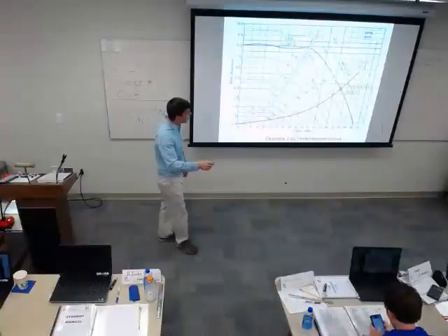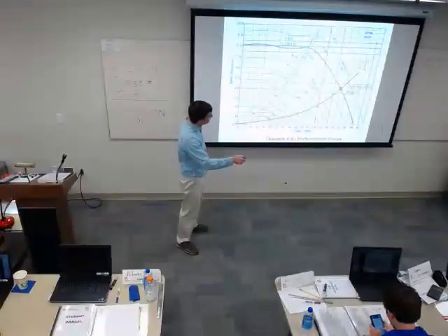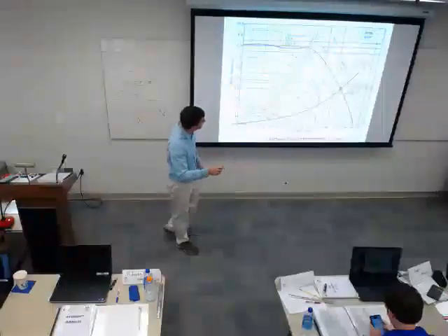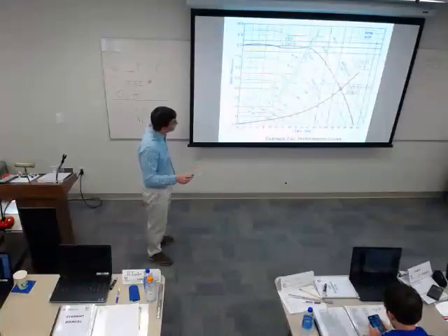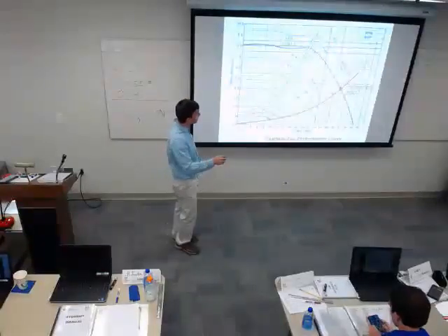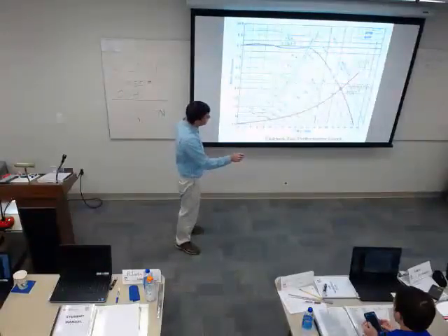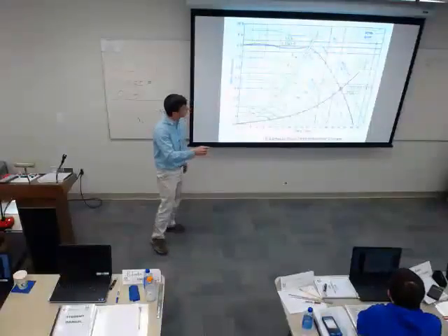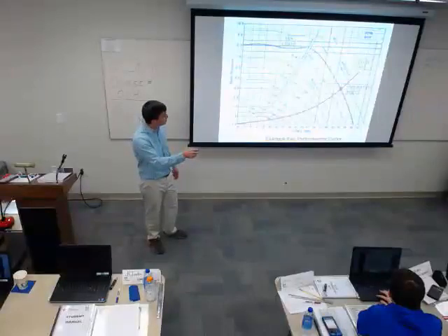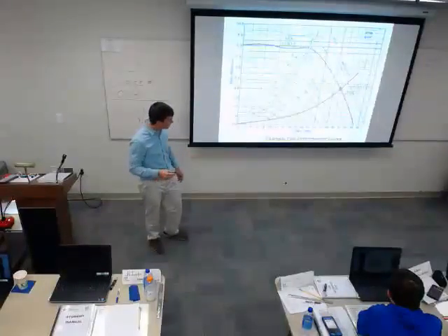Going back to one other concept here, what size fan motor would I need to accomplish this? That's not really part of this, but I want to throw that in there. My horsepower curves, these red ones: I heard 30 and 40. I would need 40. If I was operating here, I would be somewhere in between 30 and 40 horsepower. Does everybody see that? I'm in between these two at this point.